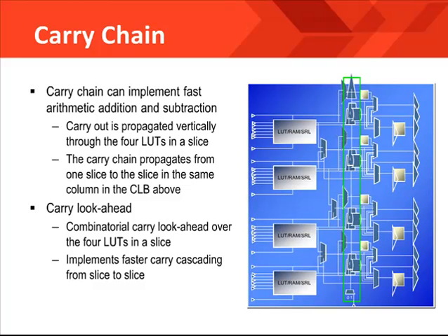This is important to note because most designs use carry logic extensively, and by using it, the least significant bit should be placed at the bottom of the carry chain. Likewise, when carry logic is used, bit ordering must be followed, with the less significant bit being placed beneath the most significant bits.